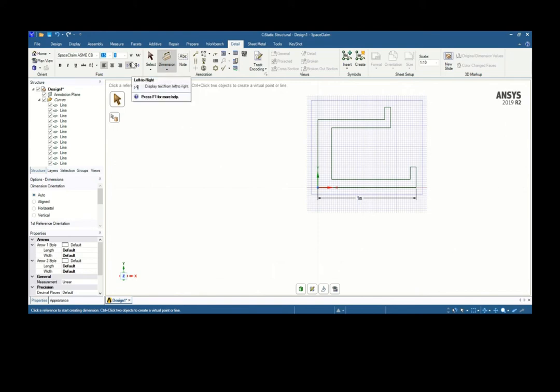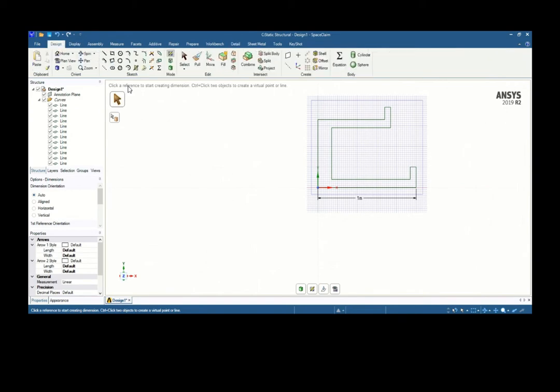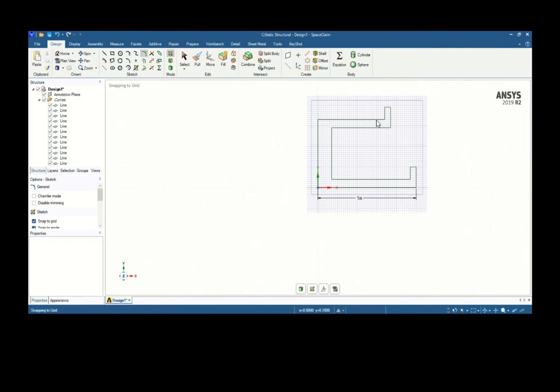Once you are satisfied with all the dimensions, then we have to round the corners of the curve, here, here, here, and these two. So we go to Design and create a round corner. Just click on this, then select a line to here. Then you choose 0.1.